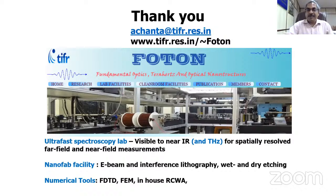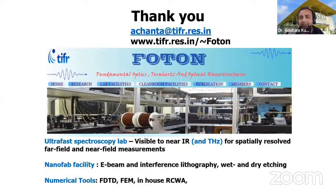For example, in the biosensor which I showed, it's basically an asymmetric Fabry-Perot structure. You have a very thin metal of, say, 35 nanometers, then a dielectric layer, and then a very thick metal layer. So it's an asymmetric Fabry-Perot. Okay, I think it's answered.